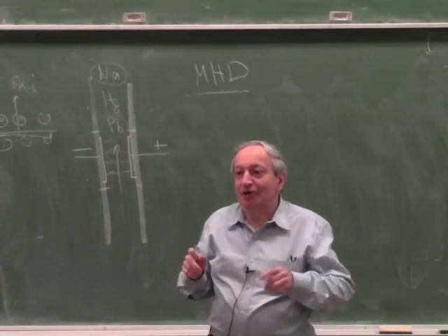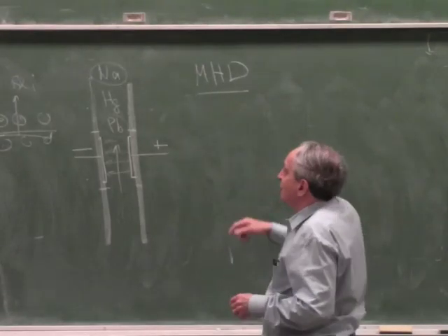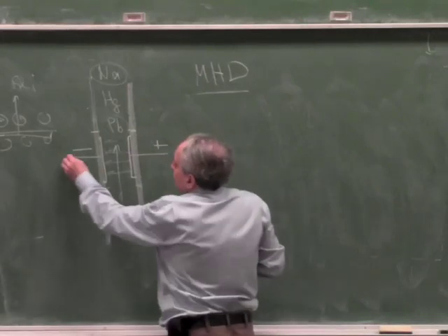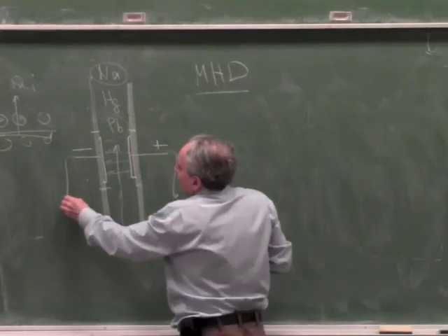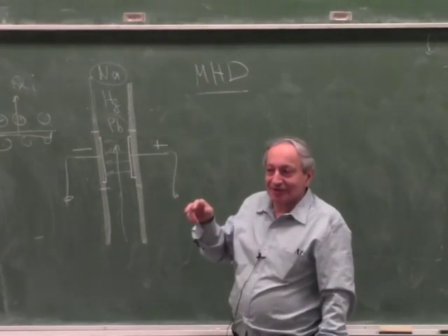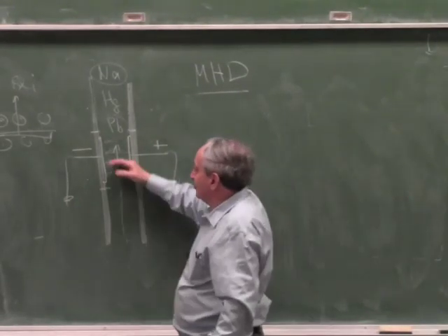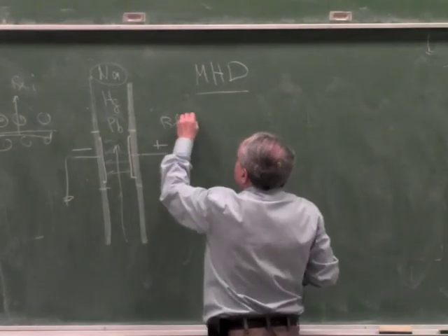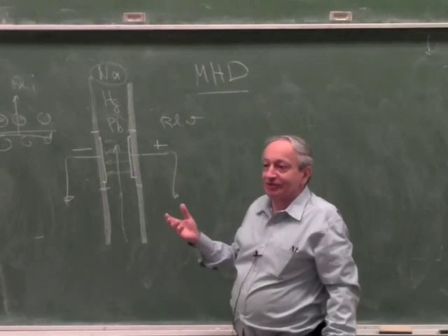Okay? Now let's talk about the opposite. If you fed molten metal and you picked up these two electrodes and looked at what happens without sending a current through it, it will be a generator. Right? Because a conductor flows through a magnetic field, you'll get a voltage, BLV, and that's a generator.